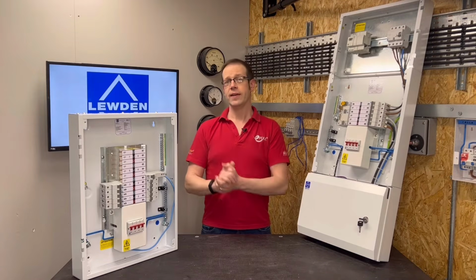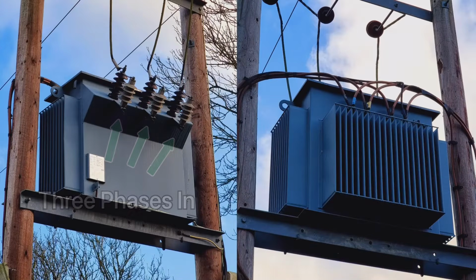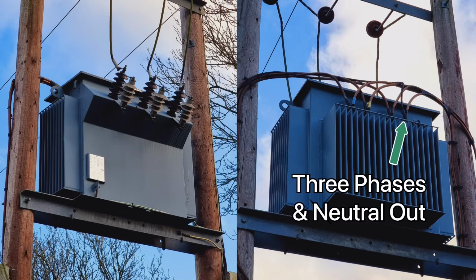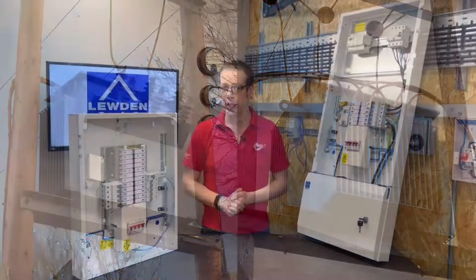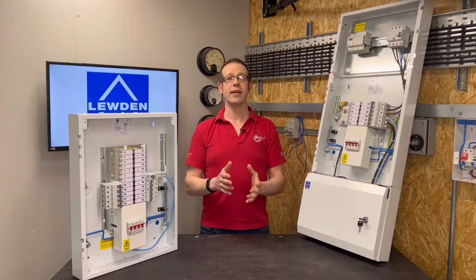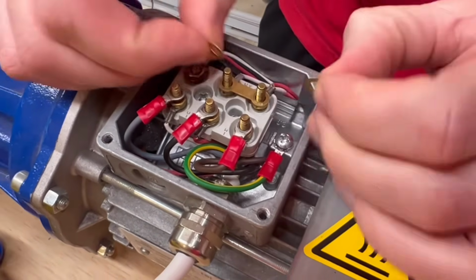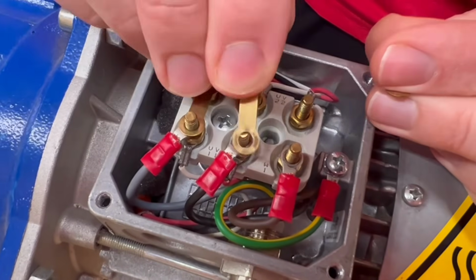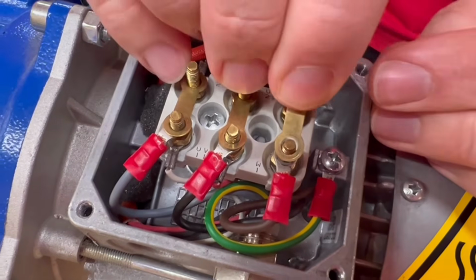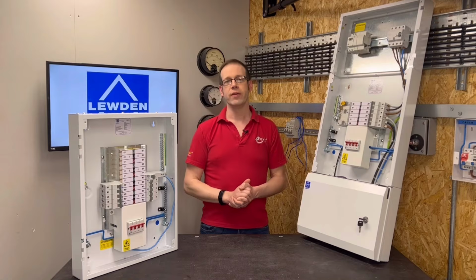Another benefit of a three-phase system is that if the generator or transformer supplying installation is connected in star, it creates an opportunity to connect a neutral conductor. This in turn allows for the connection of both three-phase and single-phase loads to the same supply with two different voltages. We can also connect our loads, which in this example are generally motors, either in star or in delta. This will give the motor different characteristics of torque and power. We can even start a motor in star and then switch to delta to limit the current that flows into the motor on startup.